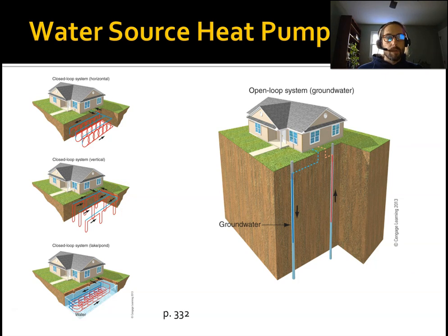And the basic premise is when you're cooling a building, you want to be dumping your heat into the coolest air possible, right? So it's easier and more efficient to dump heat into 55 degree ground water than it is 80 degree outside air.